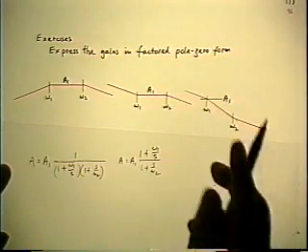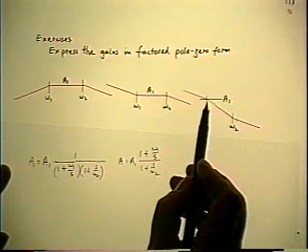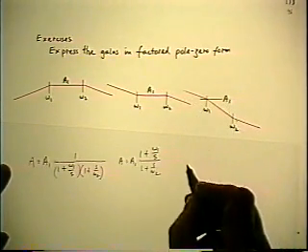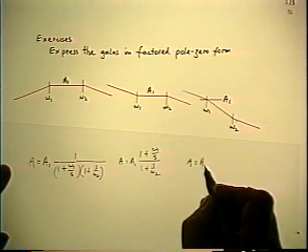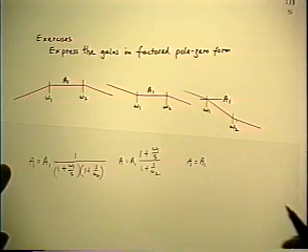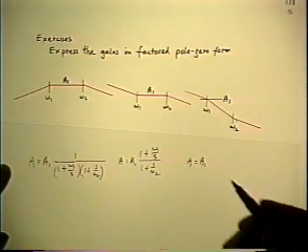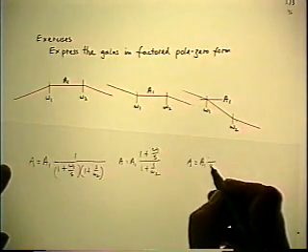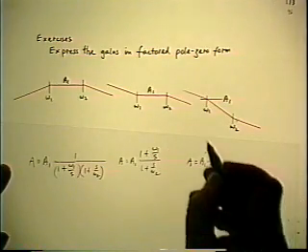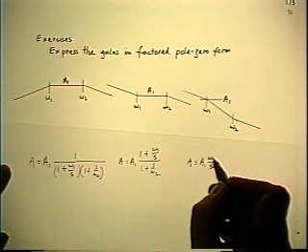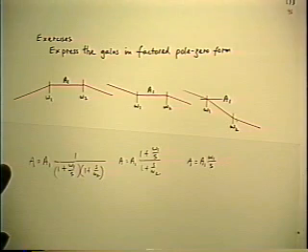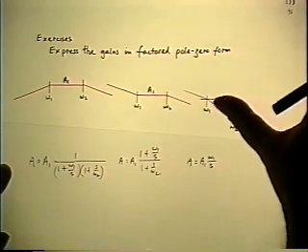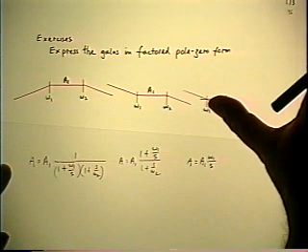So, forgetting the second asymptote for the moment, the first asymptote can be identified as A equals A1 at the frequency omega 1, but it's already on the slope. So the S term is in the denominator because it's a negative slope, and the reference frequency omega 1 is in the numerator. So the equation that I've written so far identifies the left-hand asymptote.